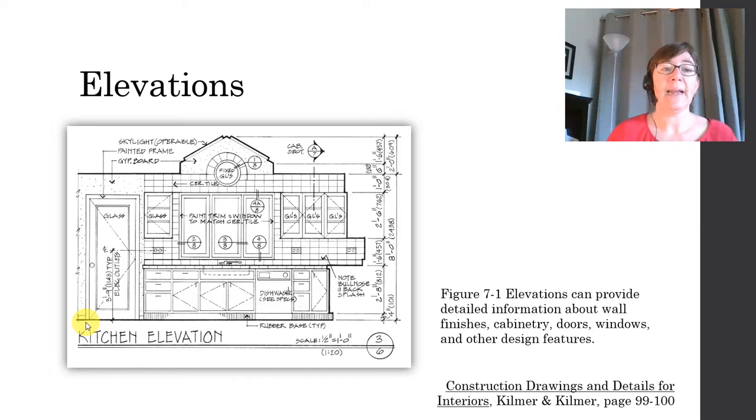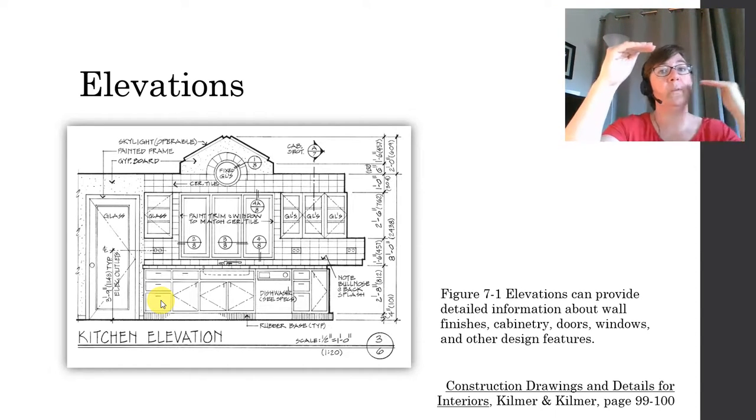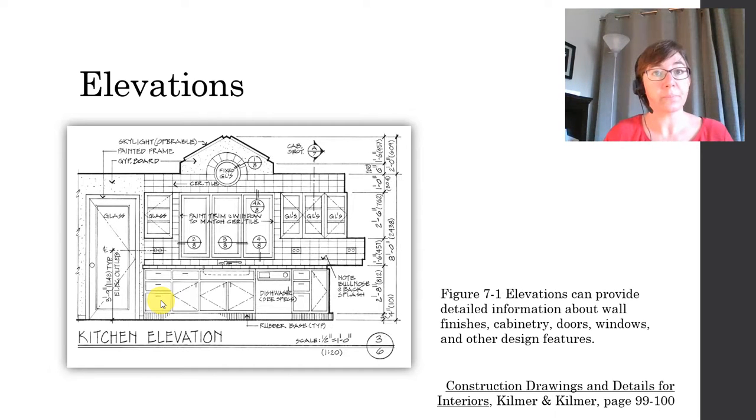And then you have the lightest line weight, and that's going to be any details such as the tile and any hatch and other details such as these drawers and hardware on these cabinets. So I want you to remember, for interior elevations specifically, because conceptually you're cutting through the ceiling, floor, and the walls, you want to make those a very heavy line weight.